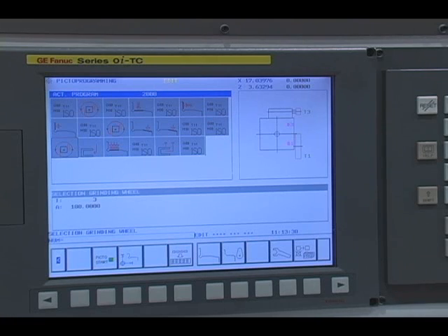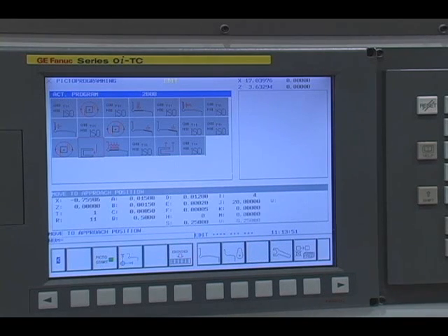I now swivel the wheel manually 180 degrees for the internal grinding wheel. I let the machine know via this icon that it's ID grinding, so I have a bore approach position. And then I did a multi-plunge and traverse on the bore, meaning the width of the bore was wider than the width of the wheel, so I couldn't do it in a single plunge. I had to do it in a multiple plunge.